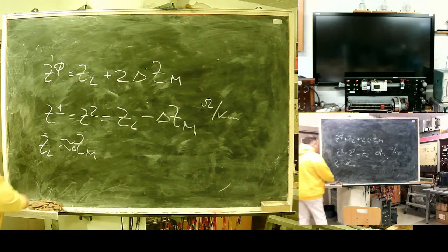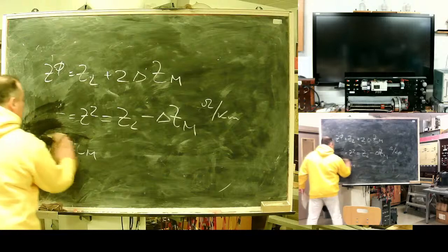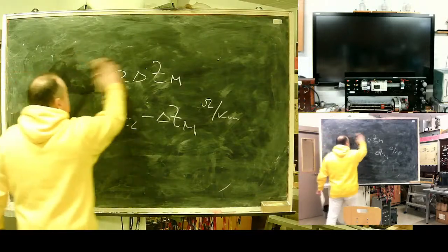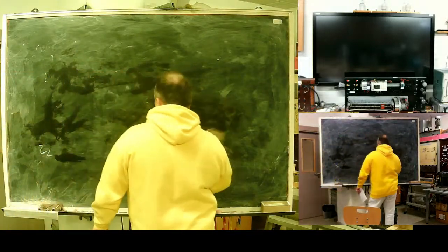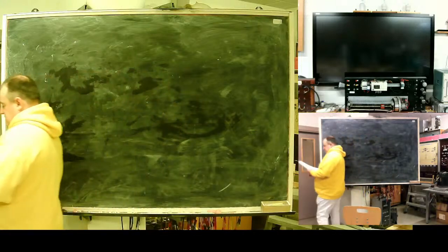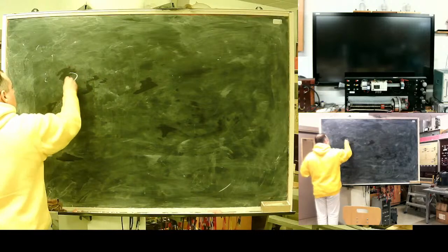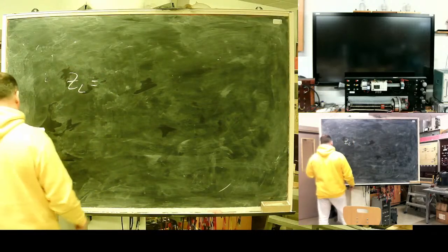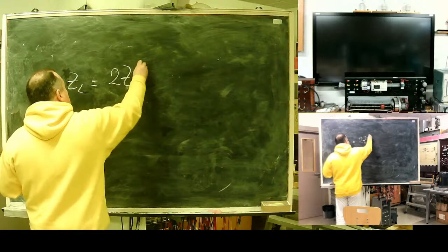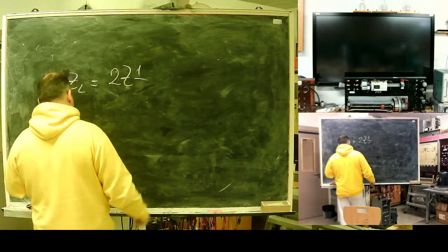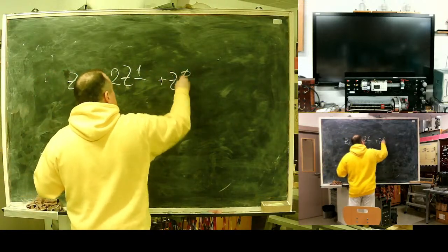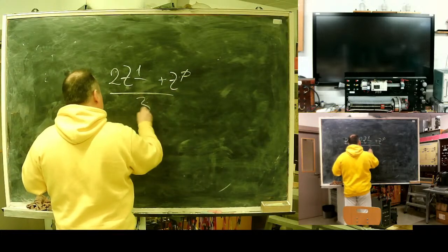We will see a huge difference between direct and negative sequence resistance. Line resistance will be double direct sequence resistance plus zero sequence, divided by 3.